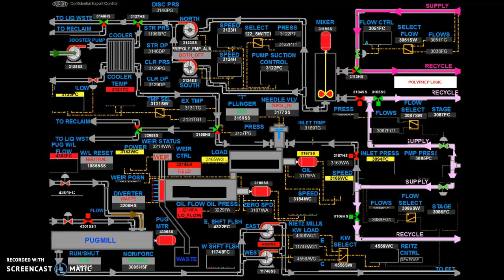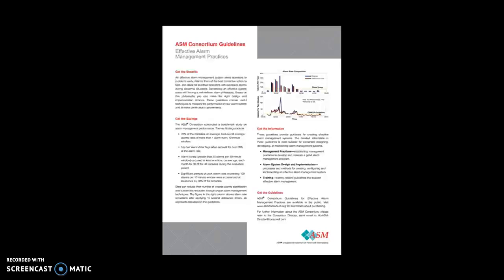For example, on this HMI, your instinct is to look for red in the same way that a red alarm on your car's dashboard means trouble, but so many objects are colored red that you don't know which to select first. Not to mention, the purpose, priority, and corrective actions for a lot of the alarms in this HMI were not rationalized. Together, these issues called for alarm reform throughout all of industry. As a result, industry leaders like the Abnormal Situation Management Consortium introduced the Standards of Alarm Management, which compel companies to thoroughly examine their control room alarm practices. This is where my project comes in.